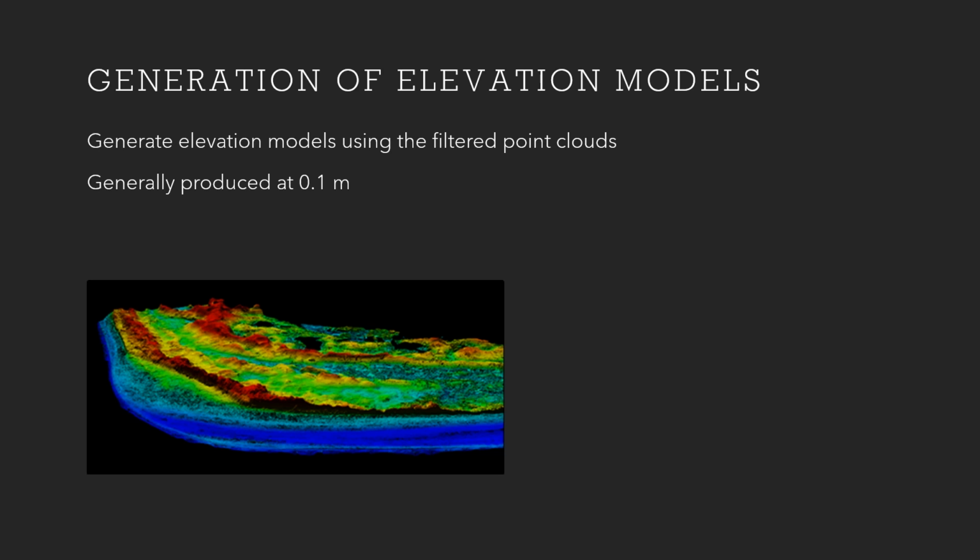And the elevation model I use that's derived from airborne LiDAR are 1 meter models, but because the point clouds are so dense, it allows us to actually get results at 0.1 meter resolution. And you can see here the elevation models in this image allow you to really get a good look at what the foredune system looks like, as well as the back dunes there.